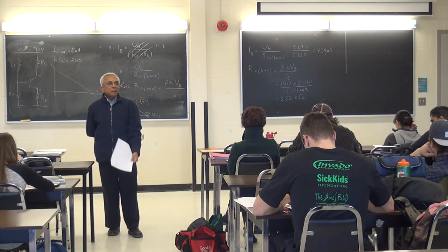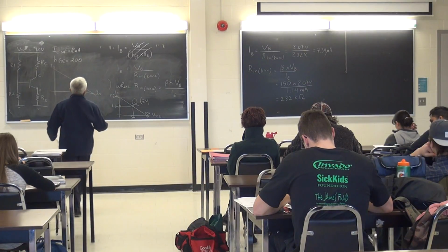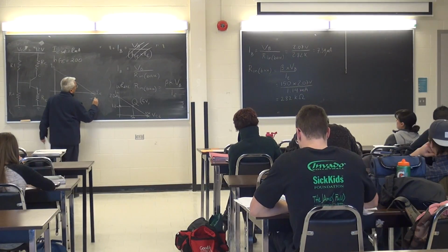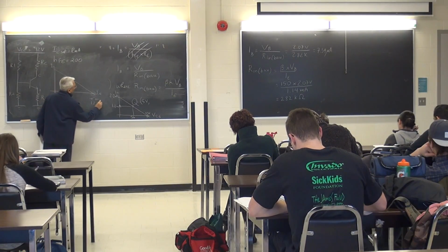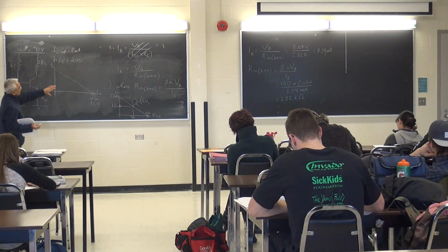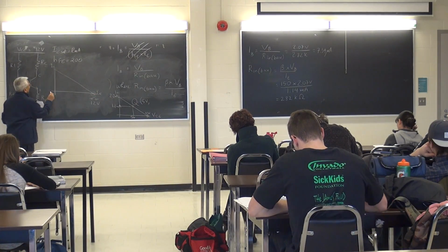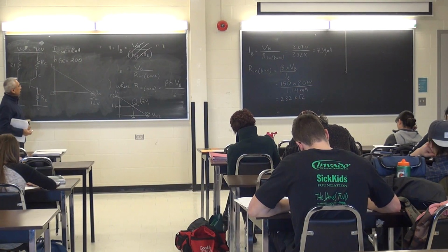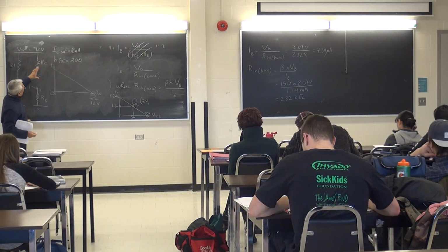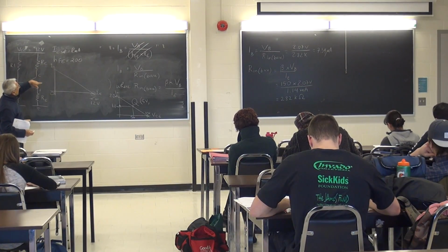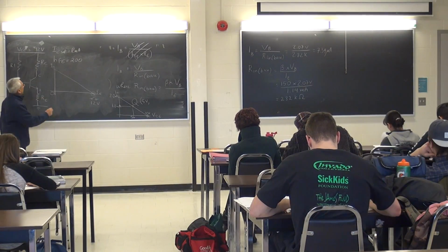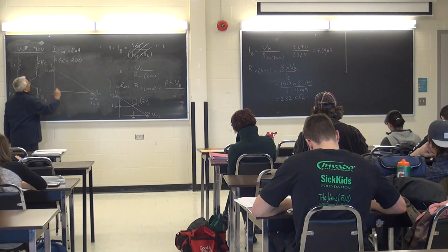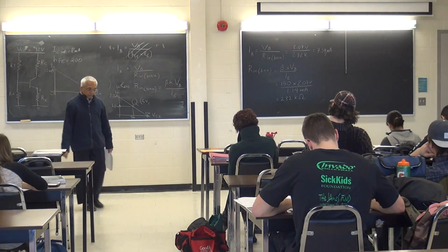So, design this circuit for midpoint bias. What is this value here? Is that cutoff? Yep. So how much is that? 12 volts. When the transistor acts like an open, current is 0, voltage is 12, same as supply. So that's cutoff. When the transistor is acting like a closed switch, maximum current flows, which happens to be saturation. Saturation is the same thing as maximum, 12 milliamps. So those are my two endpoints.